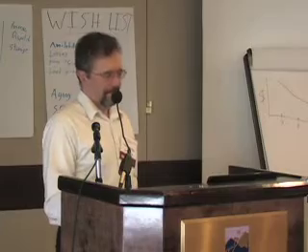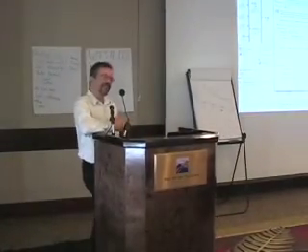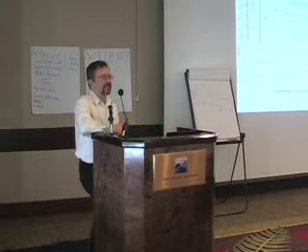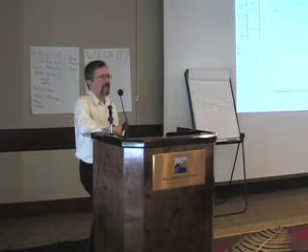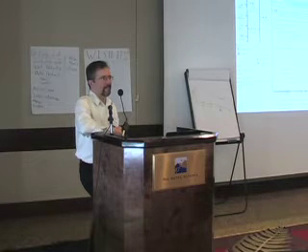Yes, Steve? So when you are trying to track state of charge and model the actual energy flow in and out of the battery, you always then choose a time step that's well below the time scale of storage that you're looking at. Yeah. Well, you need to. You should. That's a good point. That would be good modeling. You'd get silly results if you didn't do that. Unless you treat it like you treated the power cord, which is just a source of power. And you can do that for an hour time step.